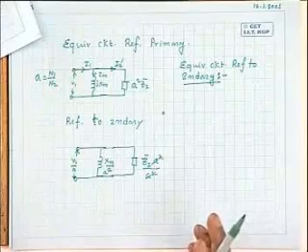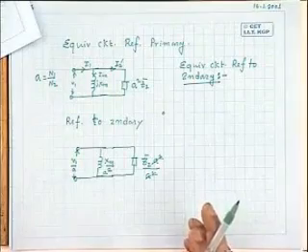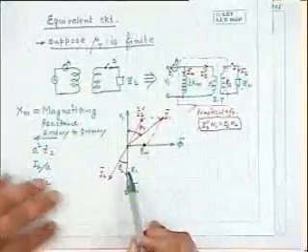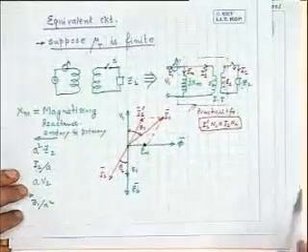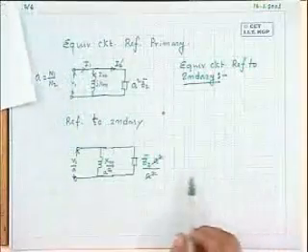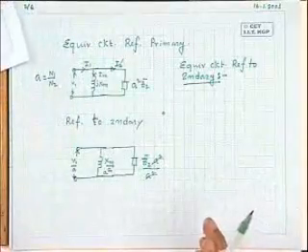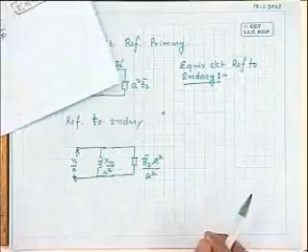So suppose at your disposal you have drawn your equivalent circuit with respect to a particular side. Don't try to go via the other path once again to draw the equivalent circuit with respect to the other side. That is just a trick. So this way one can form the equivalent circuit.